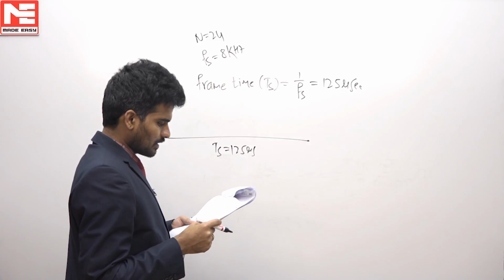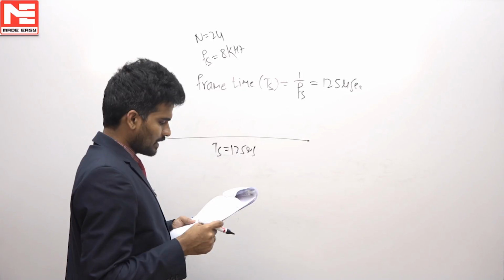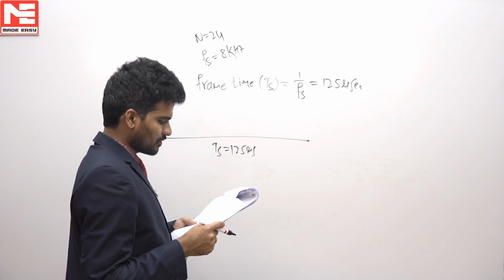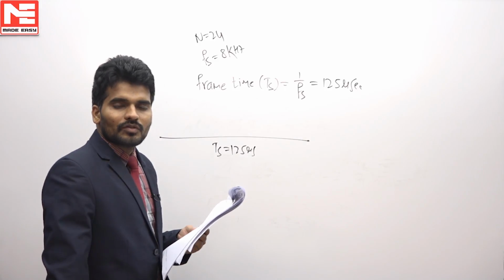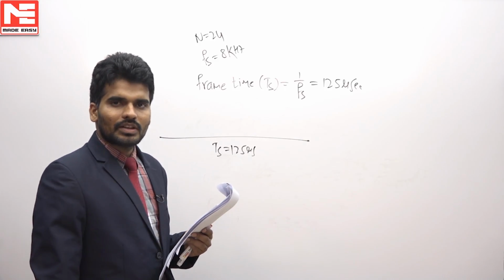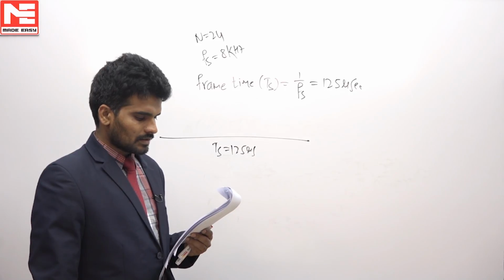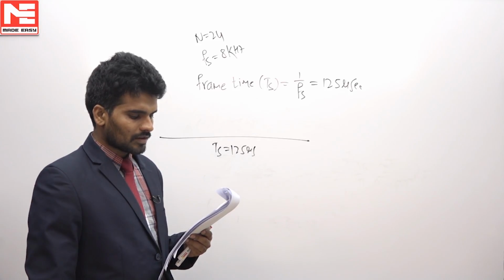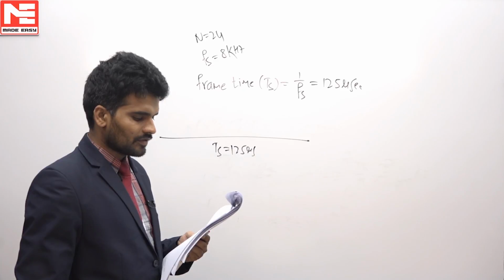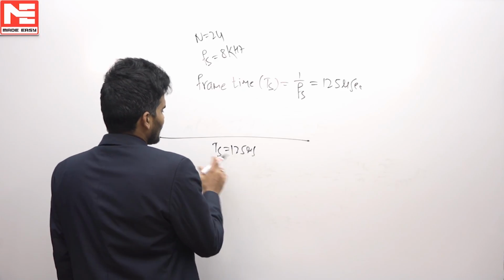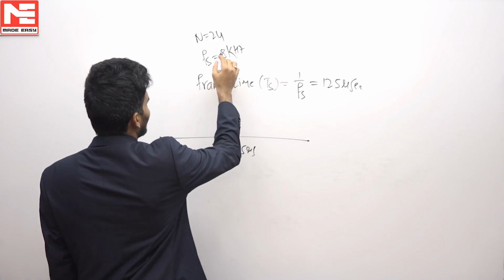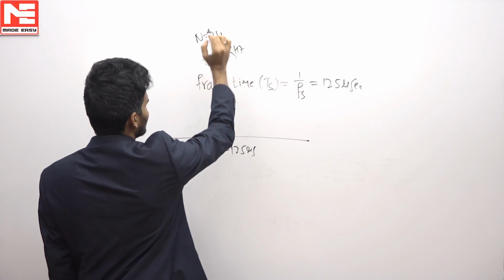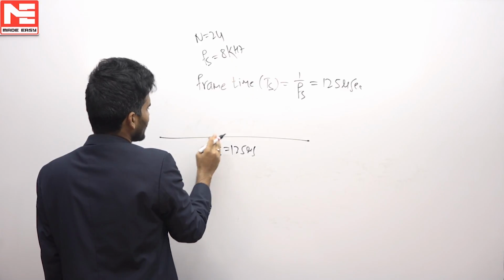And the multiplexing operation includes provision of synchronization by adding an extra bit of 1 microsecond duration for each frame. So, for synchronization purposes, in every frame 1 extra pulse having 1 microsecond duration is used. So, in each frame time Ts, 24 actual samples are present, 1 from every signal, and 1 extra pulse.